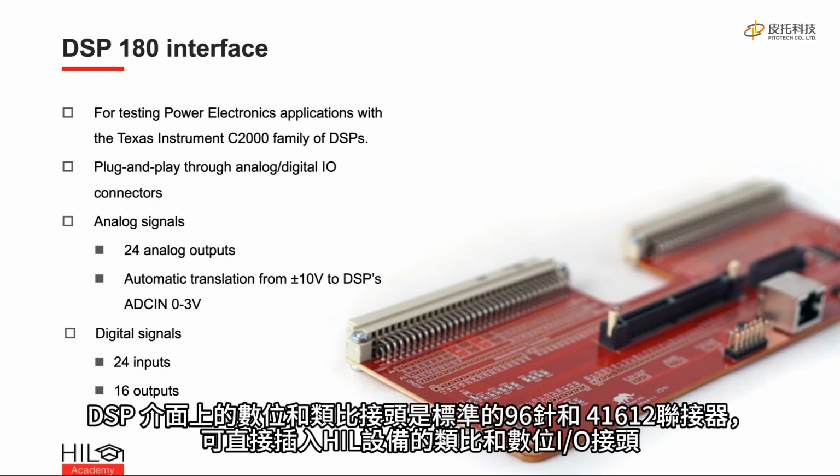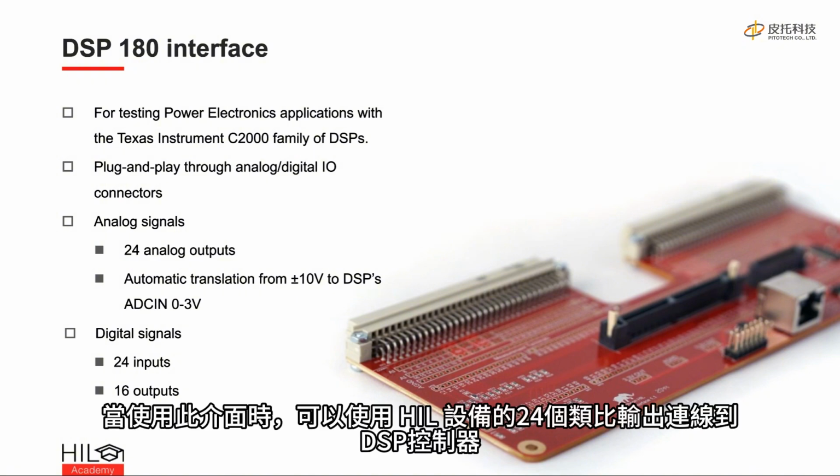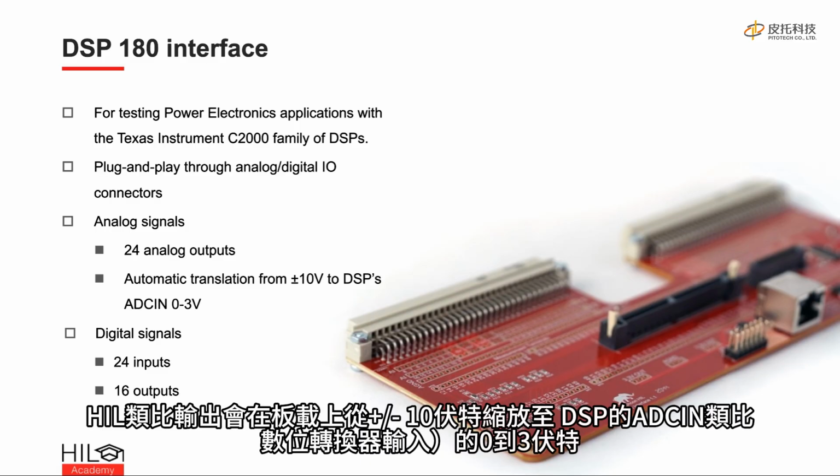Digital and analog connectors on the DSP interface are standard 96-pin DIN 41612 connectors that are directly pluggable into the analog and digital I/O connectors of the HIL device. When you use this interface, you can use 24 analog outputs from the HIL device to connect to the DSP controller. HIL analog outputs are scaled on board from ±10 volts to DSP's ADCIN, from 0 to 3 volts.